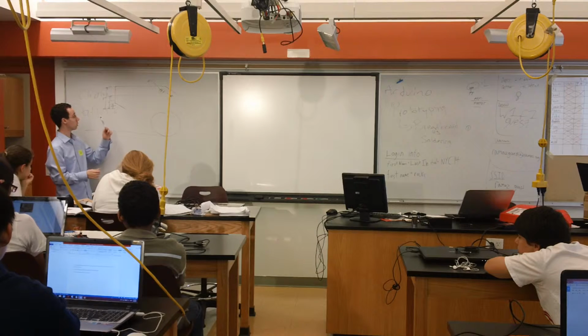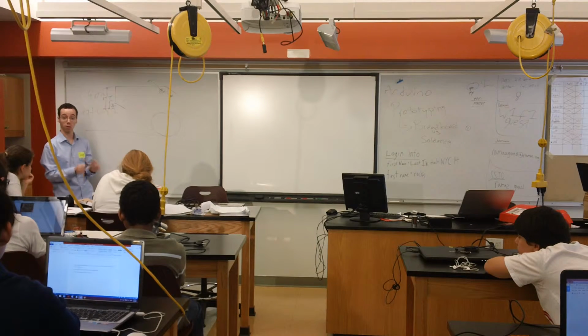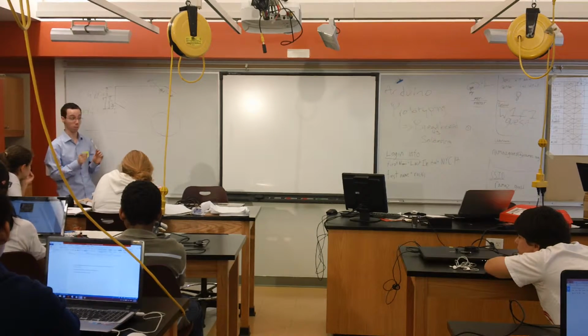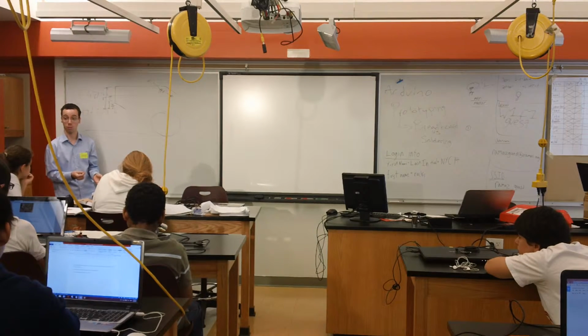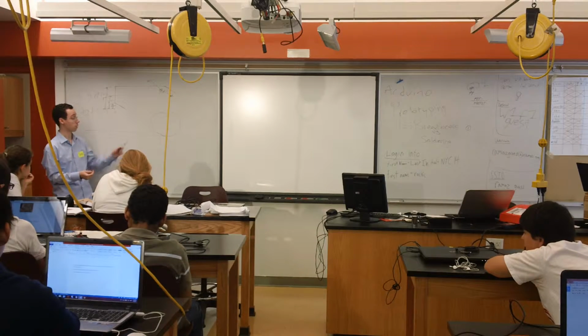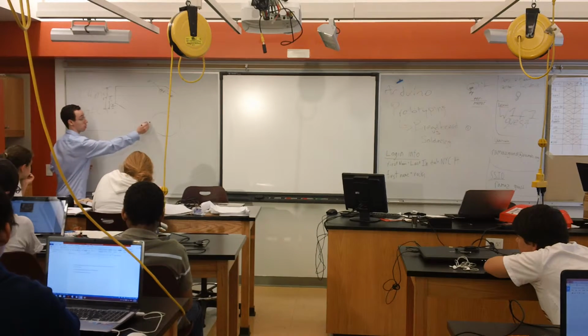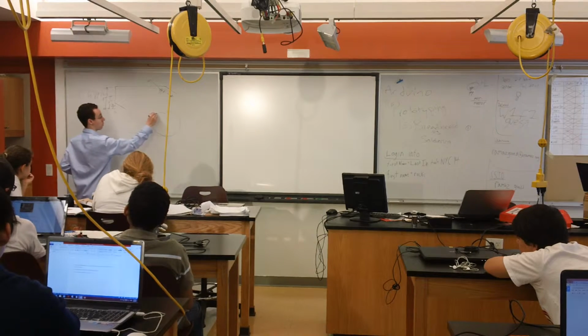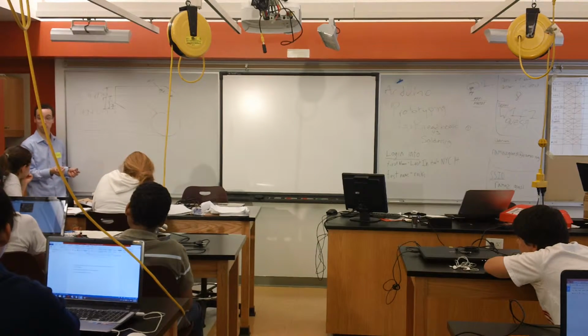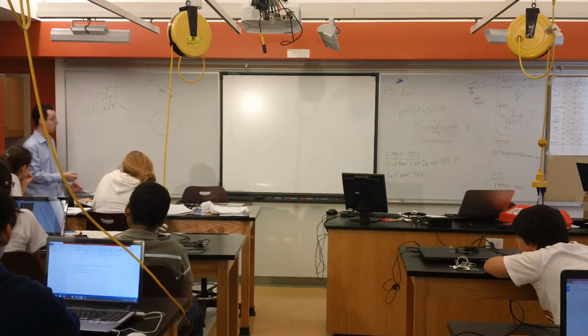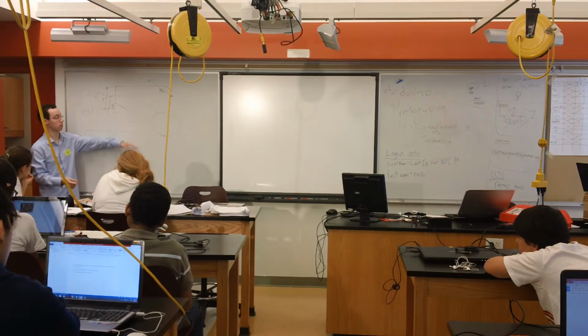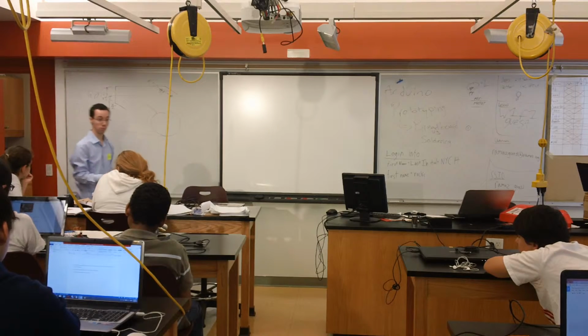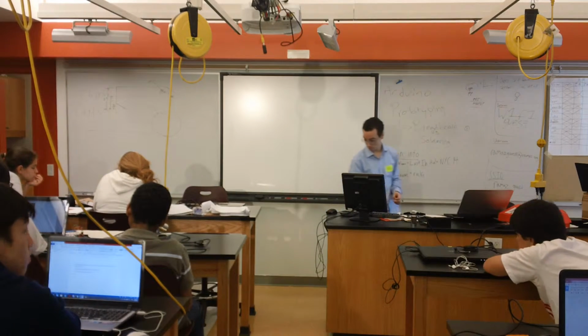So now we know the basics of how to dimension where things are, what size they are. I am going to bring up a free version of AutoCAD on the projector, and you are going to walk me through dimensioning a part, and we'll see how that goes. We don't want to put in any excess information. Like I said, I wouldn't also need to specify this if I already had the radius of this, because that's just extra information. That will confuse your machinist, because they'll wonder, why did they specify this? Is this not tangent? Is there some gap there? I don't know. Awesome. I'll bring this up.